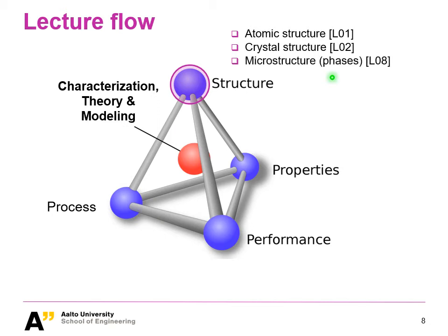That's why you finally have another definition, which is called phases. For example, if you think about a certain steel grade, you see it as a steel, and they are all BCC. But their crystals are different not only in crystallographic orientations, they are also different in their basic arrangement in terms of the carbon interstitial composition. That is what we're talking about. For example, the difference between pearlite and ferrite. So they could exist in one certain steel.